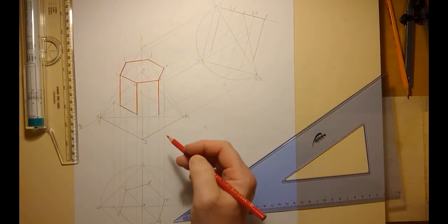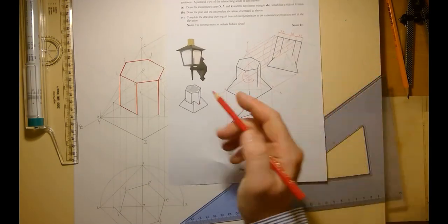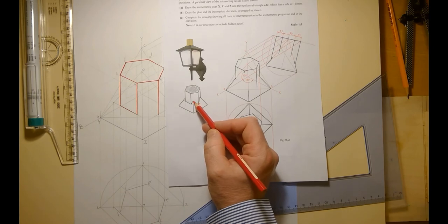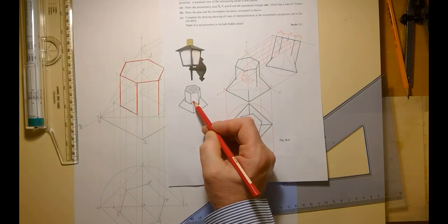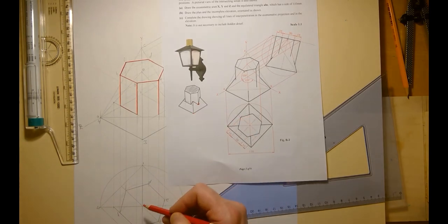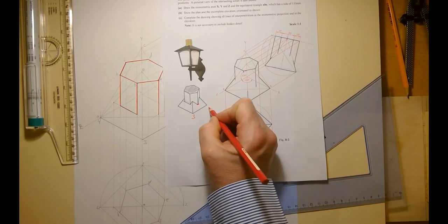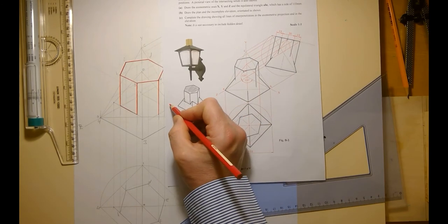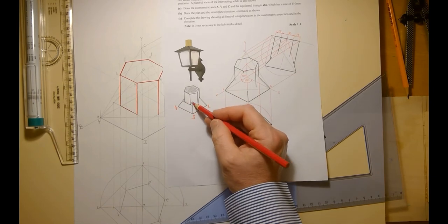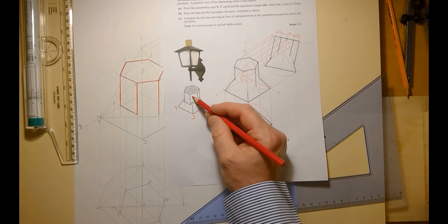Now, the next point is this section here. So that's the turning point, as we would call it in interpenetration drawing. So that point right there, I want to find exactly where that is. Now, that's on the edge that I have called 0 down to 3, okay? So that'll be my point 3. That'll be my point 2. My point 4 is over here. My 1 is at the back. Okay, so that's my point 3. So that point there is on the edge 3, which is going up to the apex of my pyramid 0.